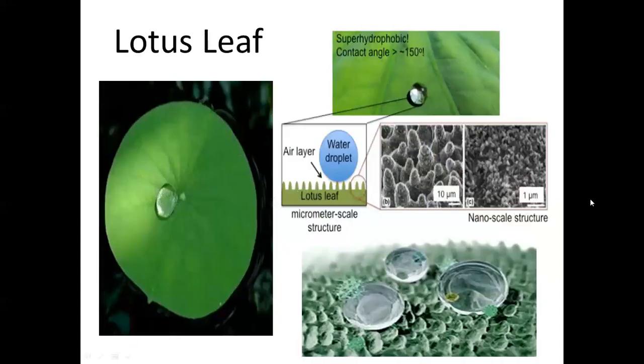So here's some more angles. We can see that the lotus leaf is typically, the angle is greater than 150. And what we can see is the model on the surface is not only that the surface has a certain chemical affinity, such as oils on there, but it also has a certain morphology on there that the water droplet actually sits on.